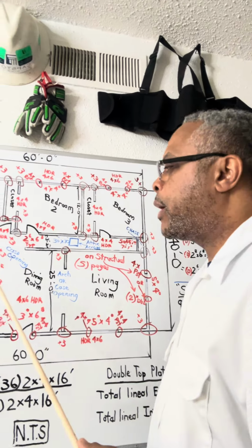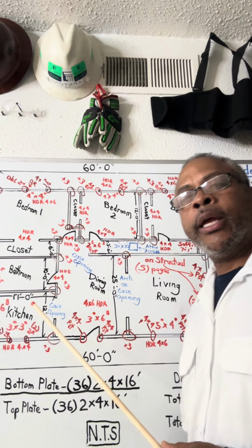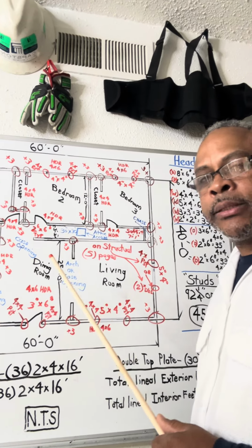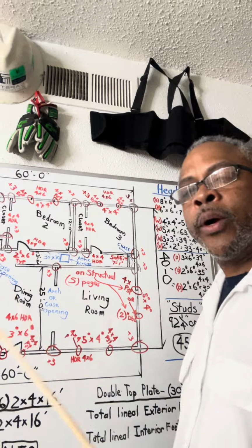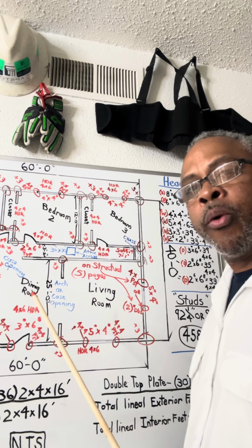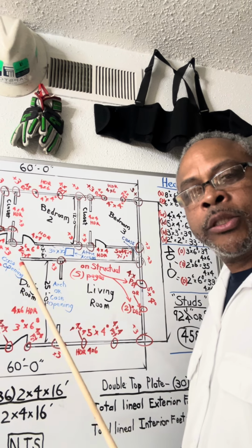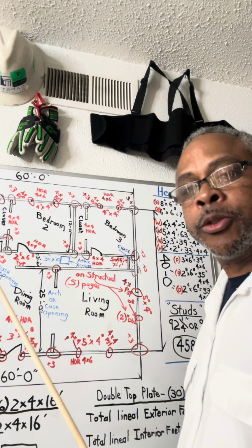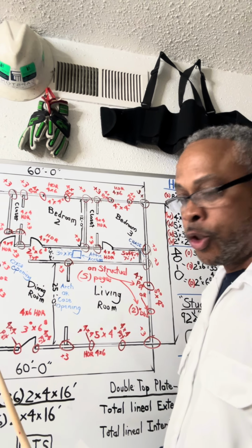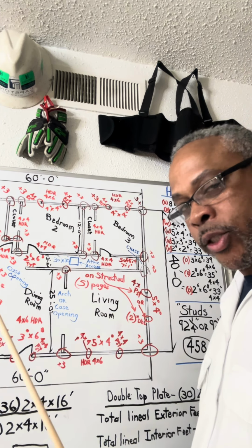You also have in your bathroom toilets, you have tub traps that the joists need to miss. You don't need to head out anything. A good joister, he'll run his layout, but his layout does jump and move around, but it stays on point with how plywood is to be sheeted. And plywood is supposed to be staggered at least over 32 inches. Don't stagger nothing 16 inches. That's not staggered.